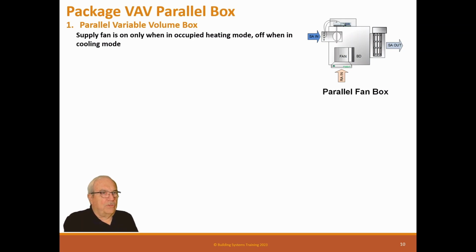When you're in cooling mode, this is a regular VAV box. So this cooling valve raises or lowers the air and it goes right to the space. During the heating mode, it sucks the air from the plenum and blows it and blends it with the VAV air to the space. So it's different. It's still running. It's on all the time. It doesn't go on and off. It's not variable volume. It's constant volume.